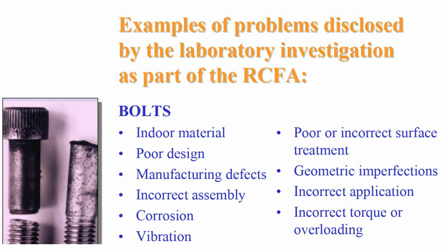Examples of problems disclosed by the laboratory investigation as part of the RCFA: bolts. Incorrect material, poor design, manufacturing defects, incorrect assembly, corrosion, vibration, poor or incorrect surface treatment, geometric imperfections, incorrect application, incorrect torque or overloading.